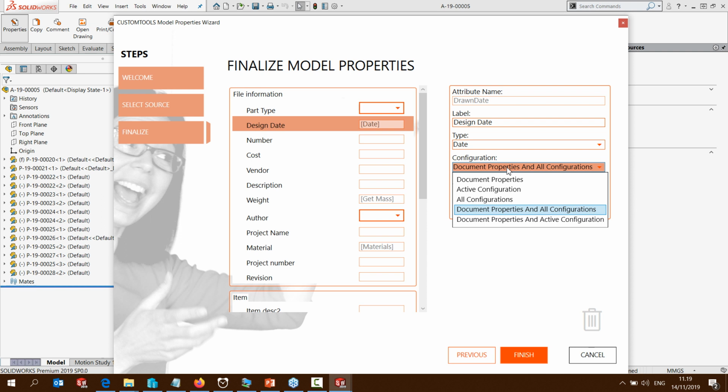Here I could also define to which properties I want the property to be written. So if you are using SolidWorks PDM, then we are also getting all those information automatically. And finally, we have the scope. So for the scope, I can define where the property should be written. Model is for part and assemblies, and here we have just for part or just for assemblies.